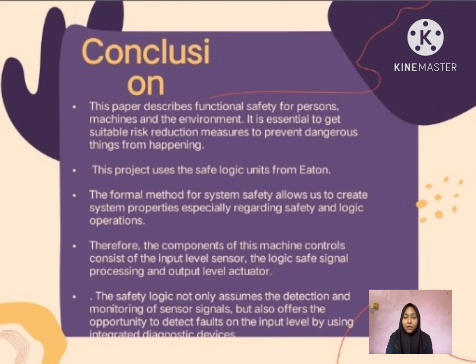Therefore, the components of this machine control consist of the input level sensor, the logic signal processing, and the output level. The safety logic not only assumes the detection but also has the opportunity to detect faults on the input level by using an integrated diagnosis device.